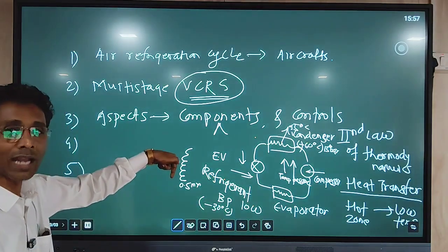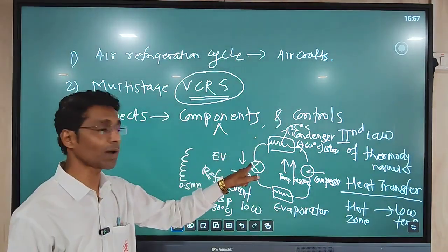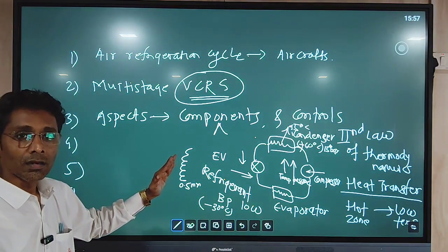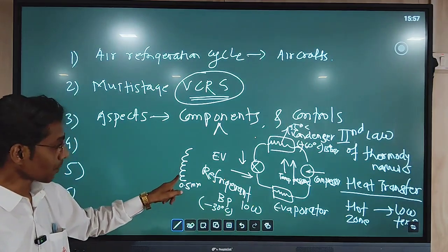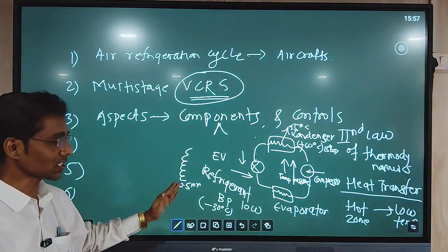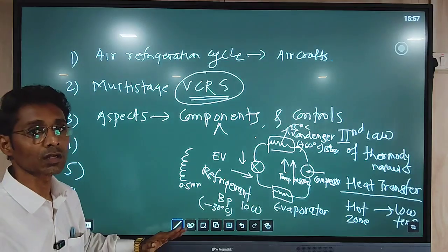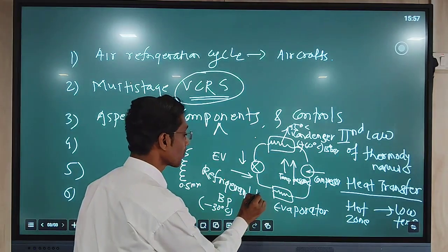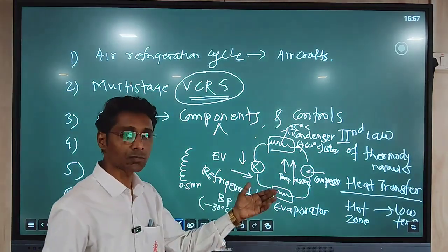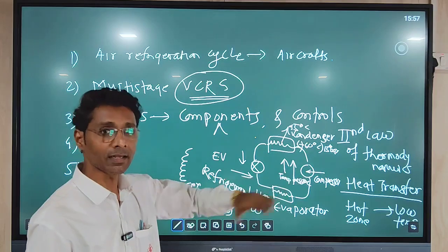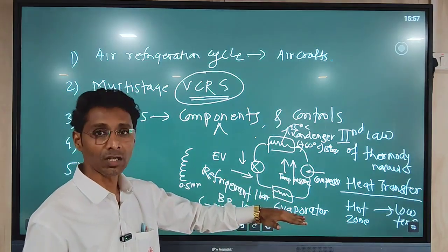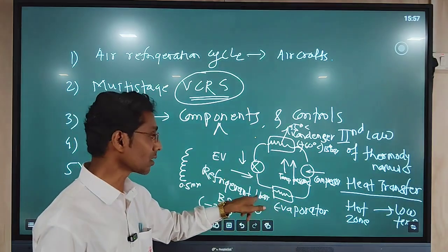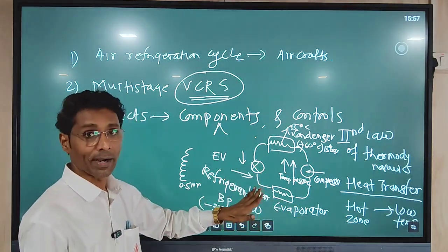Through this small diameter tube, when the refrigerant is passed, more opposition is offered by the surface or material of the tube, and a drastic pressure drop occurs. This pressure drops from 15 bar to about 1 plus bar, above atmospheric. Normally the pressure is maintained above atmospheric at the evaporator to avoid leakage of air inside the system. That is why positive pressure is required.